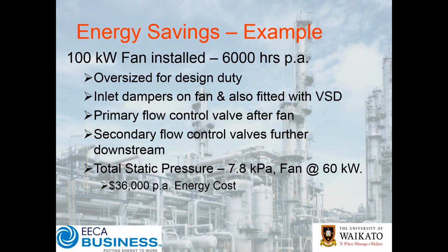It was installed and runs about 6,000 hours per annum. It was massively oversized for the design duty. Now, as part of the installation, to facilitate ease of commissioning, a range of flow dampers were installed in addition to the fan being fitted with a VSD. What was interesting is that we had primary inlet dampers on the fan. We then had secondary flow control valves further down, as well as a primary flow control valve after the fan. So ultimately we had a number of flow control dampers as well as a VSD.